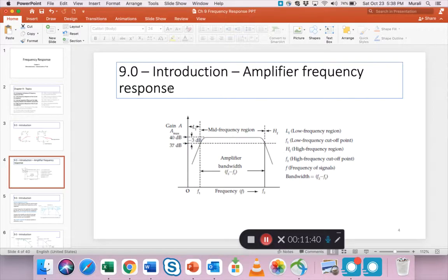So I just want you to understand that now we are dealing with amplification of more than one with real amplifiers like op amps and just BJTs and FET amplifiers also. Again, we can define bandwidth, which is the difference between the high cutoff and the low cutoff, and these frequencies F1 and F2, they are called cutoff points or break frequencies. They have many names, but the region between the 2 points, on this side where it falls by minus 3 dB, this side where it falls by minus 3 dB, that portion is called the amplifier bandwidth.